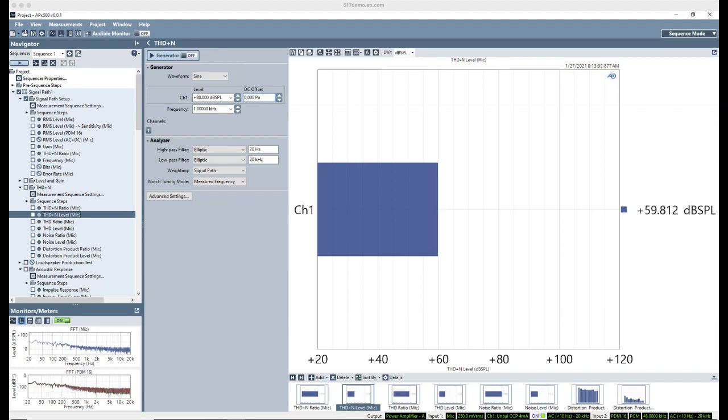If what you want to measure is the distortion of your microphone, that is a challenge very similar to the challenge of measuring the microphone's noise. In this case, the problem isn't the environment polluting the measurement. In this case, the problem is that the vast majority of loudspeakers have far more distortion themselves than the microphones that we might want to measure.